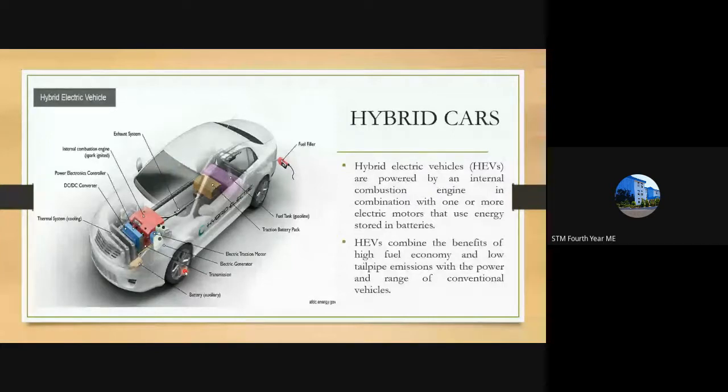When it is coming into third, fourth, and fifth gears, the vehicle is moving smoothly, so it requires only less power. So we are looking at fuel economy, and fuel economy is less during the starting conditions. At the starting conditions, if you provide an electric drive, such as a motor, then we will get high torque, and we can even reduce the fuel or completely neglect the fuel for those starting conditions. That is how a hybrid car works.